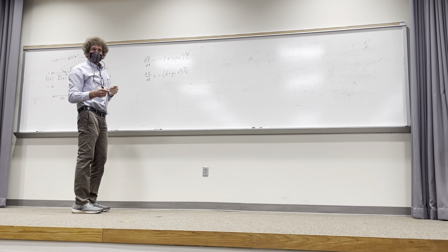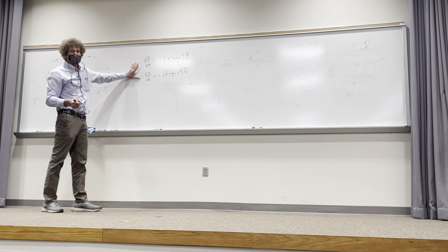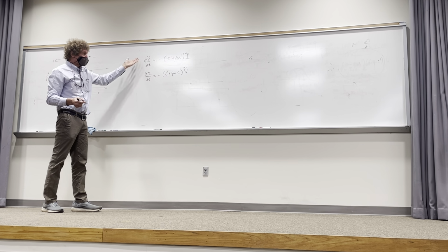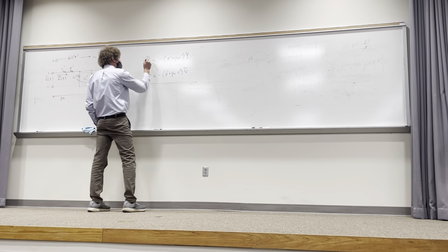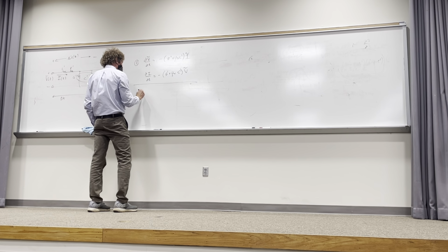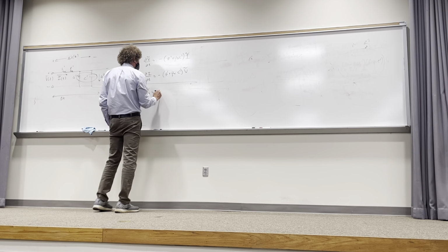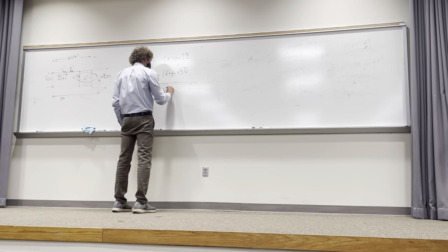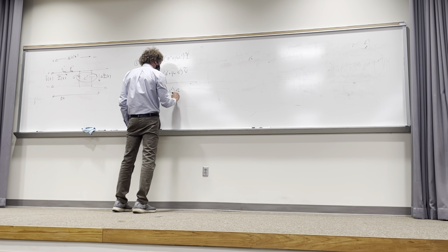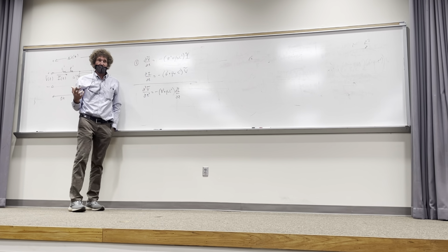So when we do this, we're going to get one equation with one unknown. And the way we always do it, we're going to take a derivative of either one with respect to Z, and then use the other equation to substitute in for the first derivative of the quantity that was by itself. So when I come here, if I take two derivatives of this, I'll call it equation 1. I get the second derivative of V with respect to Z squared equal to minus quantity R prime plus J omega L prime, and then I have dI/dZ here. Now y'all remember that from last time, right? I don't have to put the tilde there. Follow me on that, class?